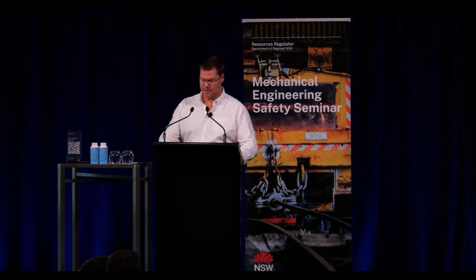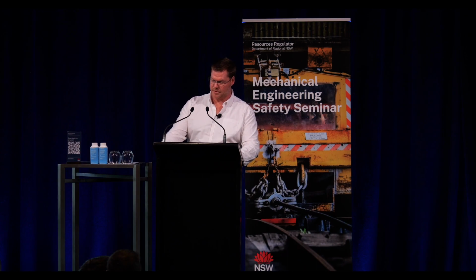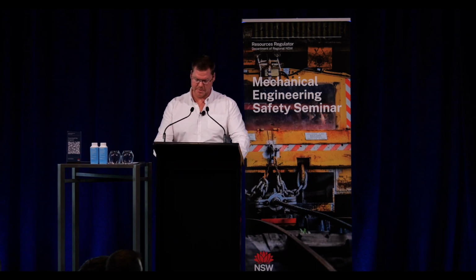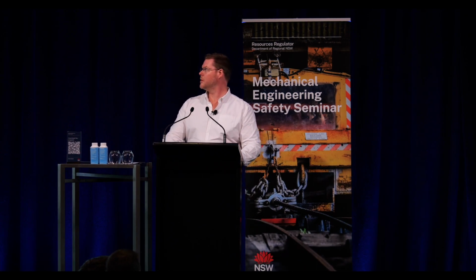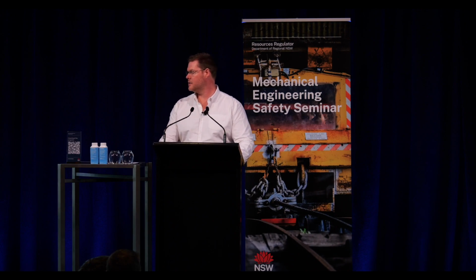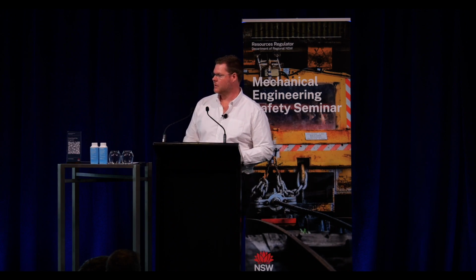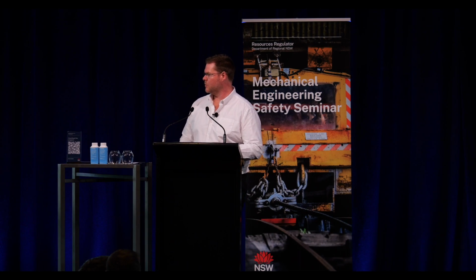So it's important to follow the manufacturer's recommendation for fleet angles for the specific equipment being used, because there are different limitations for fleet angles depending on the equipment. For example, winders have the 1.5% fleet angle limit, but winches have higher limits at 3%, and cranes have different fleet angles in their design as well.